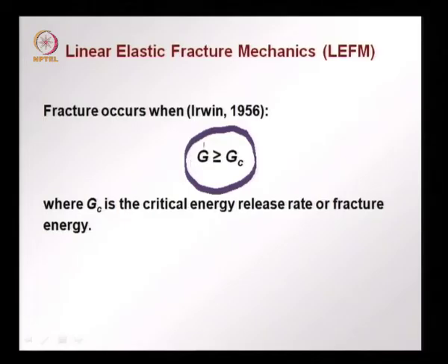This now depends on the stresses, the load applied and the body, the shape of the structure, shape of the element and the defects. This has to be greater than or equal to a material parameter, the critical energy release rate or the fracture energy. So, this also could be a failure criteria, but these two failure criteria that we have seen, K1 greater than or equal to K1C and G greater than or equal to GC, are not independent.